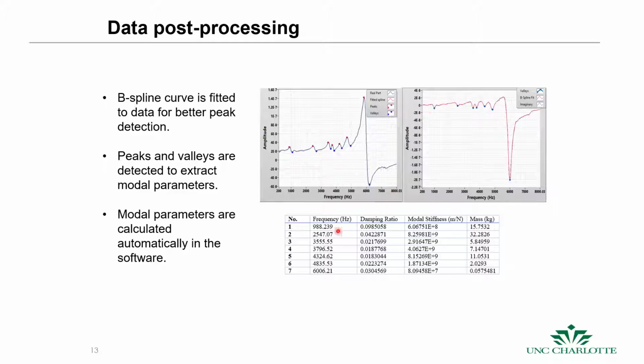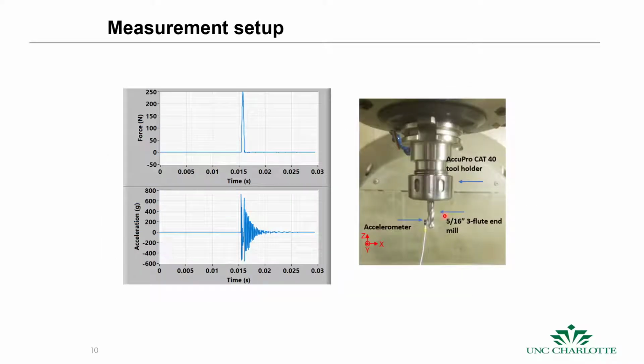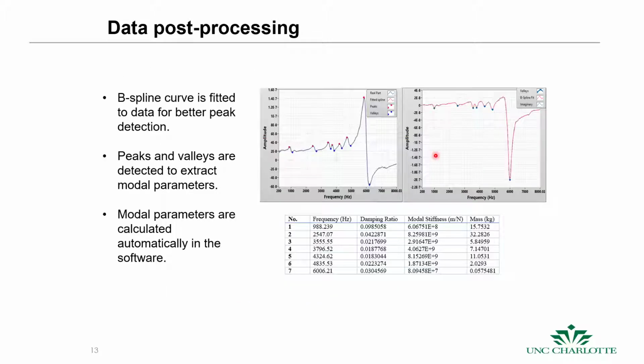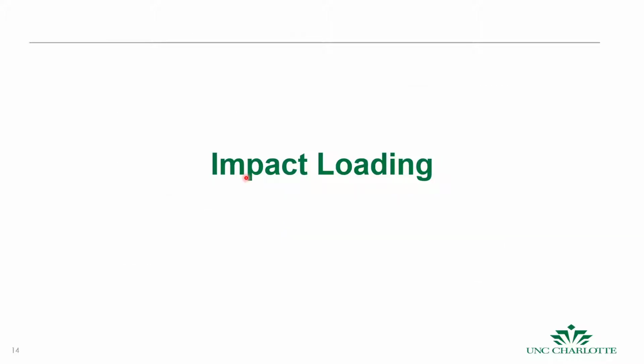Now, we got all of these responses. We had all these frequencies, and they were all present in this system here. So the dynamics of the tool and holder and spindle and machine dynamics can all come into play when we're looking at this. Even though some of these are a lot stiffer than others, you can see that even in this large continuous system, we have a lot of different frequencies that show up. Okay. Now for our research, we'll use this to predict chatter and then try to stay away from frequencies that we know will have higher energy than others. Okay.